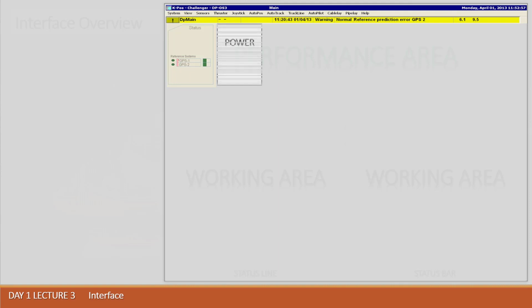Next icon is known as power. It shows you the loads which the system has right now at the moment, and it shows you the amount of power buses available in your configuration. In case the main bus tie breaker between the main buses is opened, then here you will have two bus indication, and information about connected or opened bus is also shown here. Also you can see the load bar which shows you in green load still 60%.